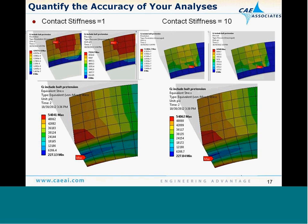So here, in this particular example, the contact stiffness was set to 1, which predicted a penetration of 10 to the minus 6. Contact stiffness was increased to 10, penetration of 10 to the minus 7. We got an order of magnitude less penetration. It resulted in a different contact pressure pattern. We had 7,000 here. We get a local singular kind of edge effect here. But if we look in the center section here, our values are fairly similar to that 7,000 value.